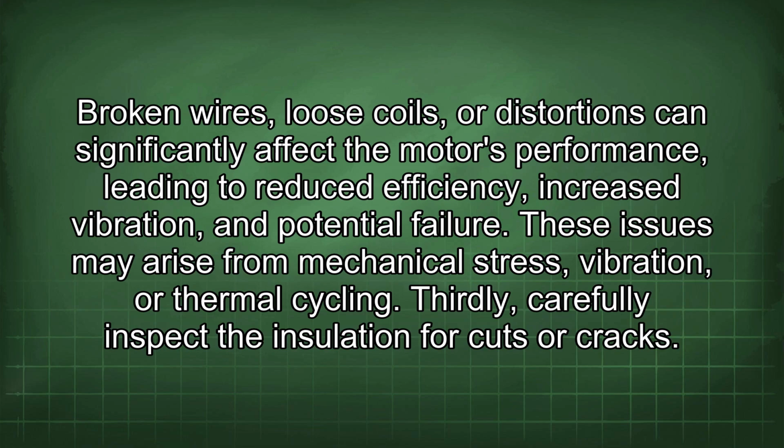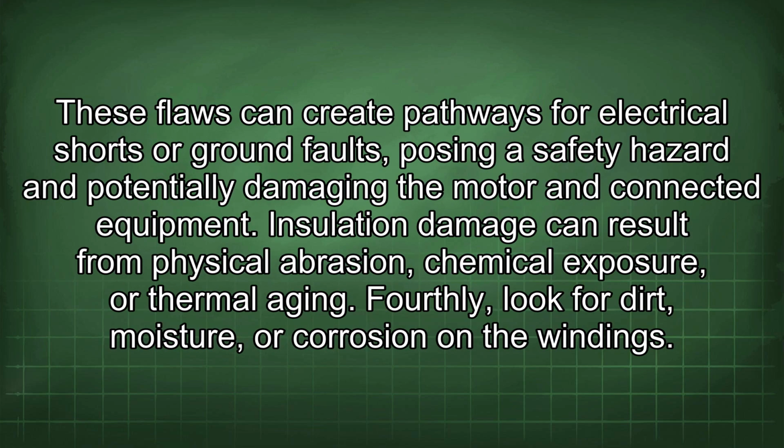Thirdly, carefully inspect the insulation for cuts or cracks. These faults can create pathways for electrical shorts or ground faults, posing a safety hazard and potentially damaging the motor and connected equipment. Insulation damage can result from physical abrasion, chemical exposure, or thermal aging.